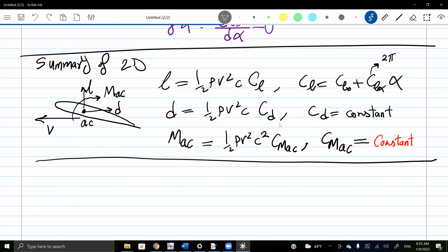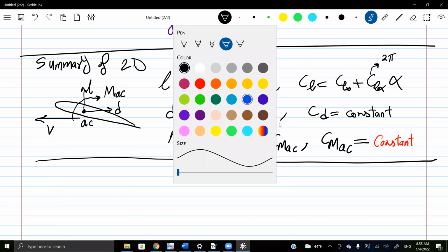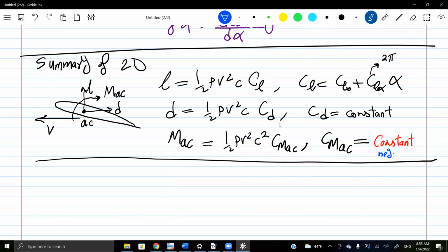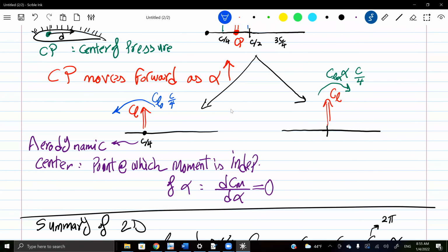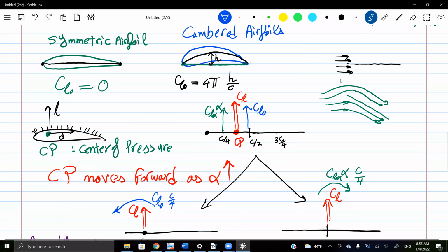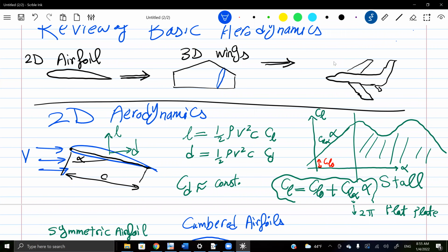Yeah, you said that the moment is usually a negative constant, right? Yes. So in the above diagram, it shows positive. Could you explain how it's usually negative? Sure. Let's first specify what is positive and what is negative. What is the sign convention? The sign convention for pitching moment is pitching up is positive, pitching down is negative. So for this airplane, pitching up is positive, pitching down is negative.